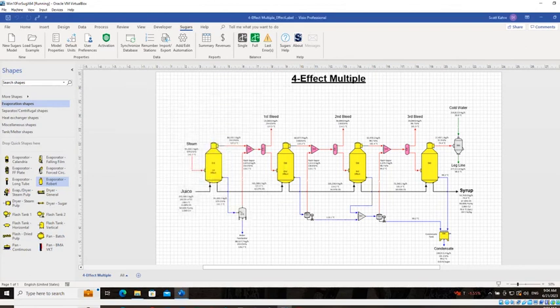And now on to a little bit more exciting stuff. First of all, the evaporator station has seen a couple of new improvements. The first thing I want to mention is if you're using an existing model that was developed in a previous version of Sugars prior to 4.4, in order to gain access to these new evaporator features, you're going to want to replace the evaporator station in your model by dragging and dropping a new one from the stencil here in Sugars 4.4. So that's what I've done in this example model.